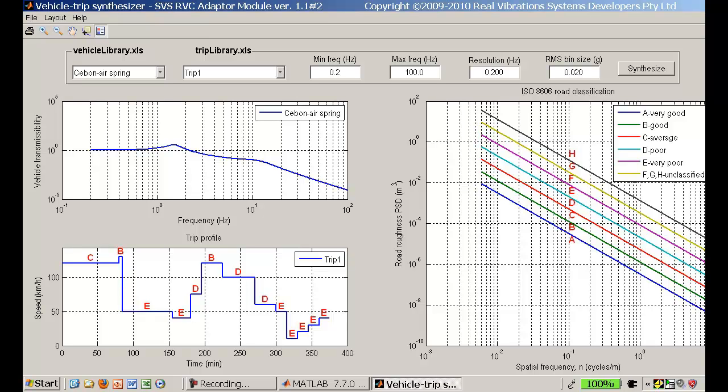These main ingredients are, firstly, a model that describes the spectral characteristics or spectral density of the surface elevation profile of pavements. These are shown on the graph on the right of the screen. These spectral models are used by the International Standard Organization and have been found to be an accurate representation of road profiles, sometimes known as road roughness. It is interesting to note that the shape of a spectral function doesn't change. Instead, the RMS level changes with road roughness.